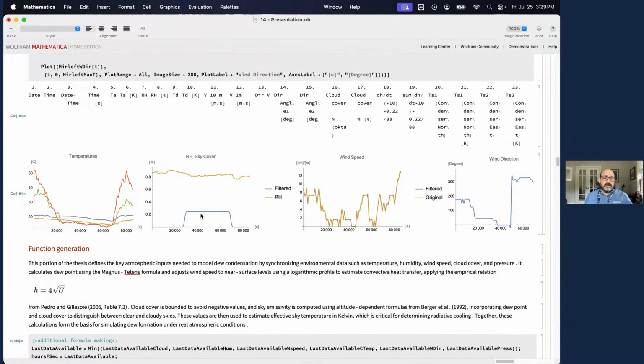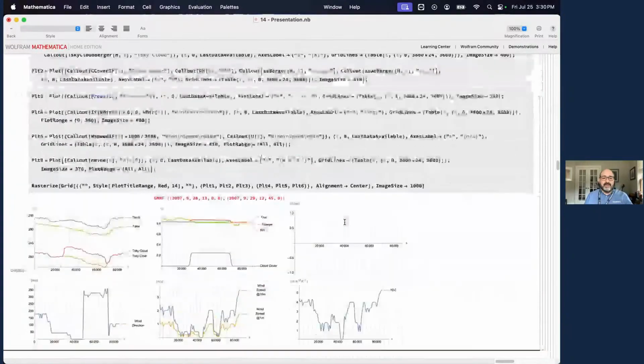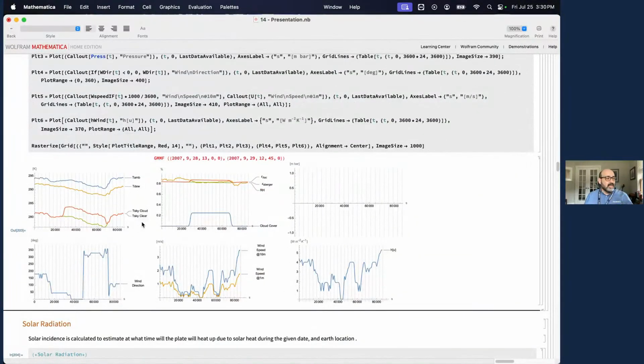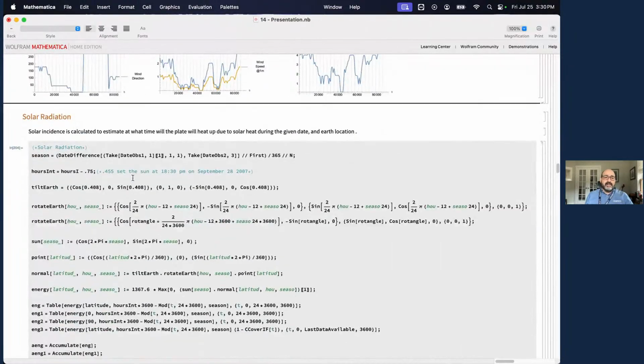So now you want to convert that into an interpolated function, and each one of these curves is interpolated. The next step is basically to take your data and make it into a nice function. If you want this data to be injected into the heat equation, it better have no steps, right? It has to be smooth transitions. That's something you've got to think about. When you inject in real data, it has to be smooth transitions. Otherwise, you're going to have trouble solving it in Mathematica.